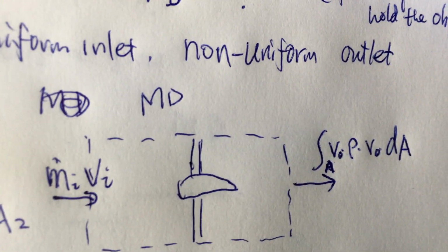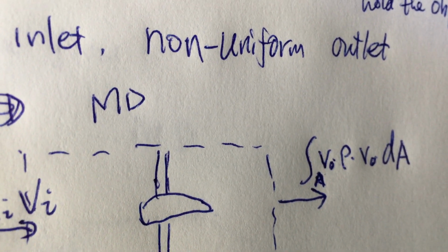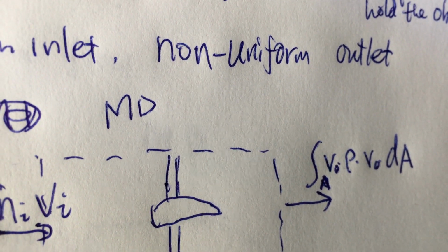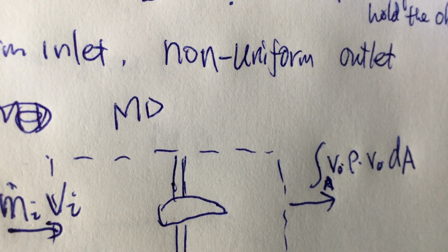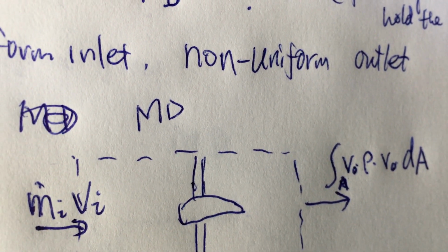So this is the expression. Again, very important, this is the expression. You cannot separate these two V's, V times V, in the integration. You cannot say, hey, separate them, one is mass flow rate and the other is velocity. No, they are together.